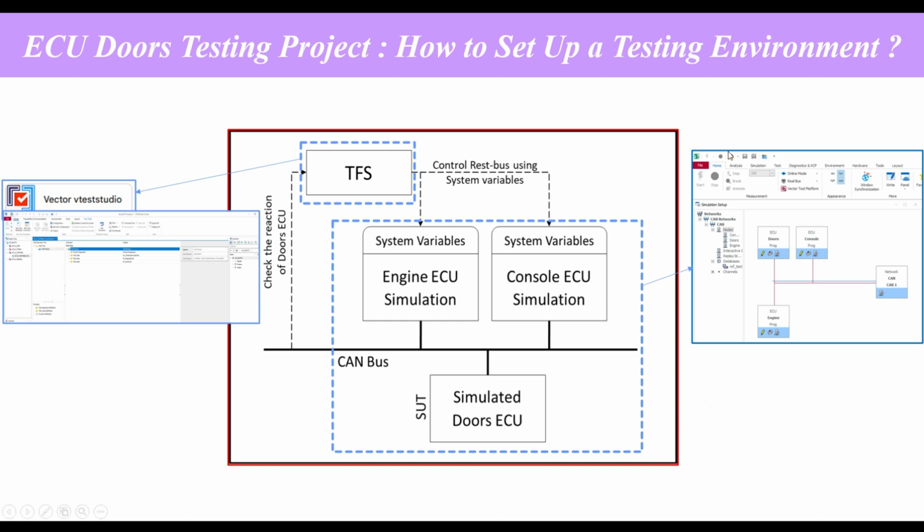This is an overview of CANoe, which allows us to reproduce the vehicle network behavior. Our vehicle network is the CAN bus. So we will use CANoe to simulate our ECU under test. This is the first thing. And also, we will simulate the engine ECU in CANoe.